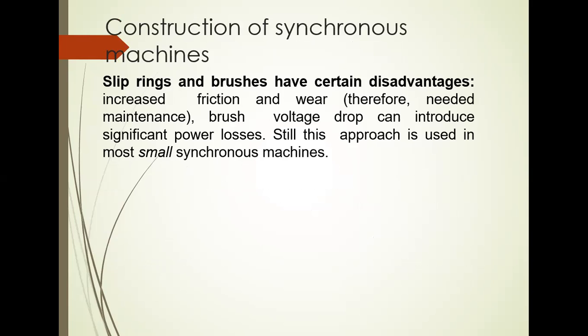So what are the limitations of slip rings and brushes? Here it induces some friction and wear. Brush voltage drop can introduce significant power losses. But the slip ring and brush assembly is adopted for small synchronous machines. Already I told.